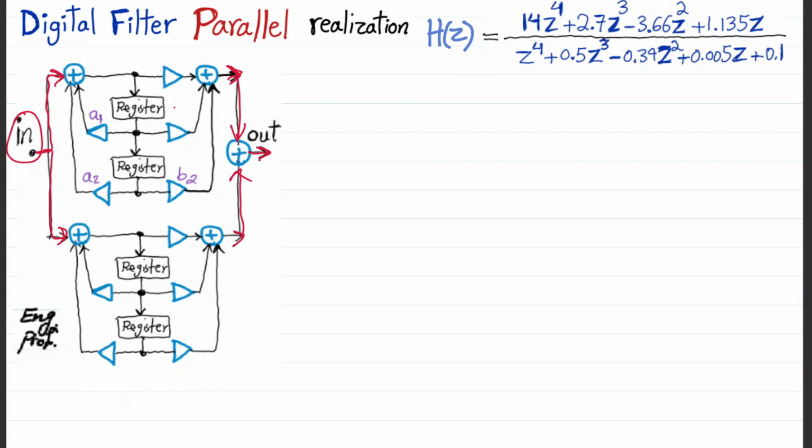How can we come up with the values of, say, coefficients b0, b1, b2, a1, a2, and also the other 5 coefficients? Each of these second-order systems has 5 coefficients. To do so, I need to be able to rewrite this H(z) in the form of, say, z squared plus some coefficient times z plus some other coefficient, and then the corresponding numerator polynomial,